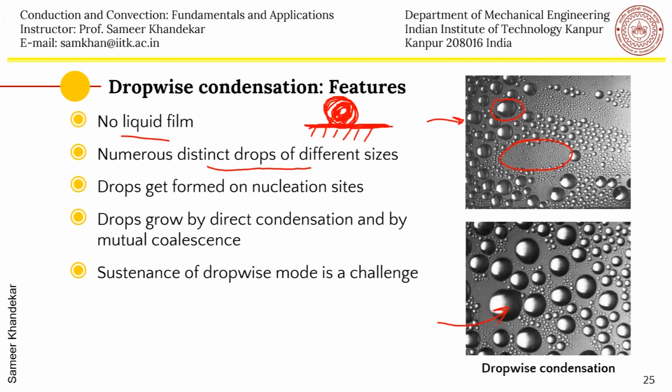Now, as you know, this particular coating which makes it hydrophobic is a challenge: how to keep it hydrophobic for a long time, because after a while these coatings get eroded, they get destroyed on the substrate, and then the hydrophobicity doesn't remain, the drops will not form, and therefore it will tend towards film-wise condensation. So how to create engineering substrates which are hydrophobic in nature, and where this hydrophobicity is sustained over a long period of time, has been a challenge for quite some time.